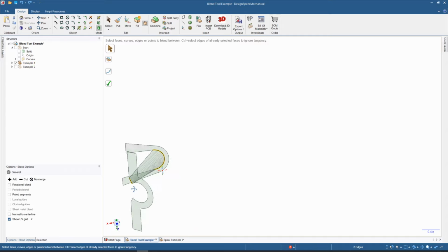But you are the one that has to make sure that the surfaces you are combining together actually create a solid. Remember, to make a solid, all of the perimeter edges have to be connected.